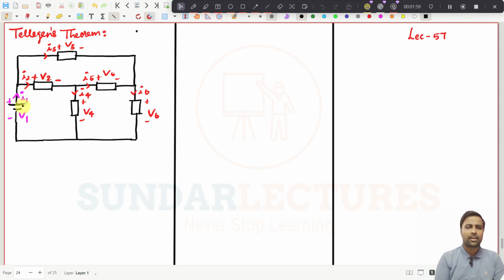Take this example network. This current I1 is flowing from minus to plus, so obviously this element, maybe a voltage source, is delivering power. See all the other elements. This is an element; you don't need to consider it as a voltage source, resistor, inductor or capacitor. It may be anything. The voltage across this element is V2, plus here and minus here, and the current flowing through it is I2, from plus to minus. So obviously this element will absorb power.